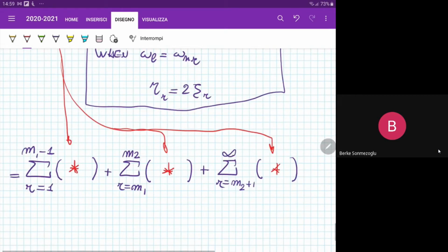So having said that, what I just tried to write is that my summation is telling me that the dynamic behavior of your system at whatever frequency is the composition of all the modal contributions that we consider as the partial fraction expansion, like the one that we are used to have in terms of residual terms, the numerator, and the poles of the system, the denominator.